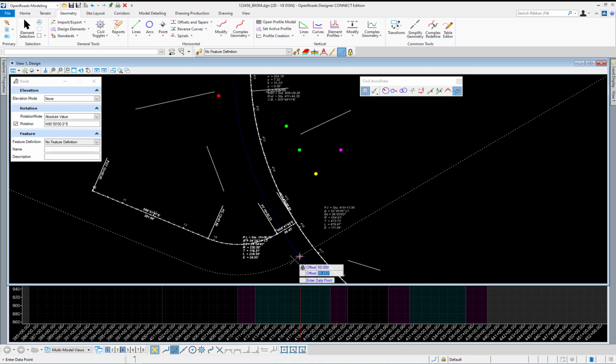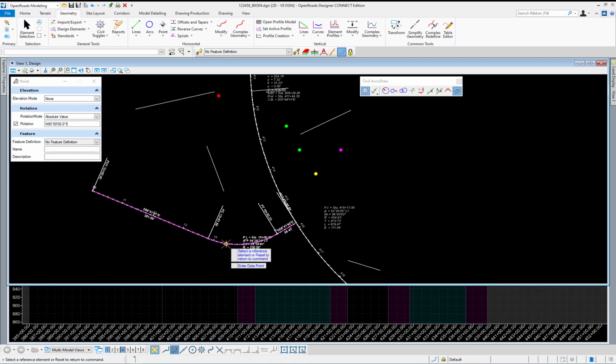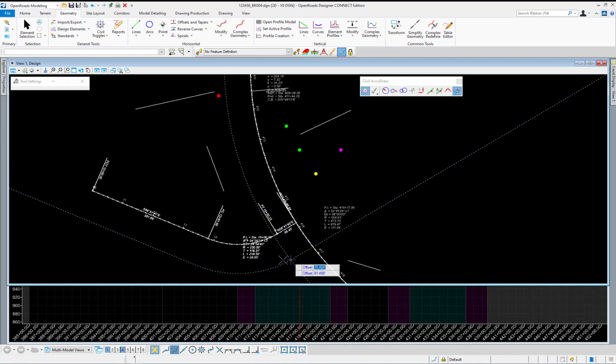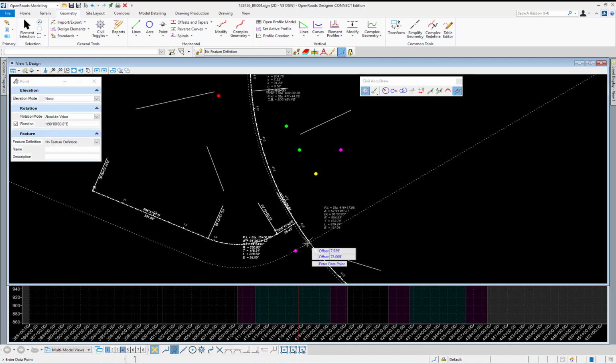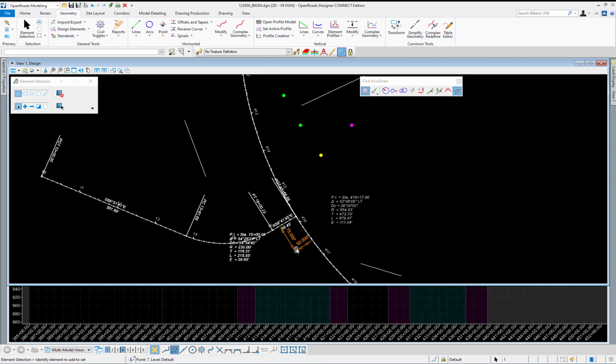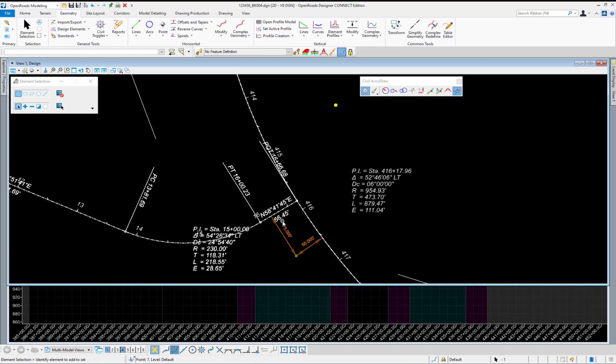Now I'll press O again to select the center line of Jameson Road, and I want to make the offset from there be 75 feet. Now data point to accept again, and my new point is now 50 feet from the center line of 185 and 75 feet from the center line of Jameson Road. These are just two examples. You can add as many as you might need.